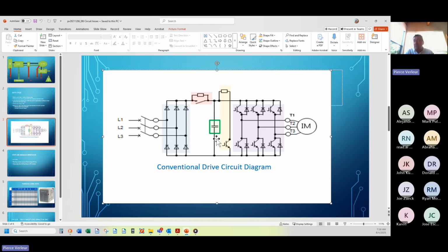Now, the way that the drive protects itself from overvoltage, a little bit of a segue here, but please listen carefully. When the drive is a 480 volt input drive, this DC bus is going to run at a nominal 683 volts DC. When this motor is lifting the load, that DC bus is going to drop. It may go down as low as 600 volts.